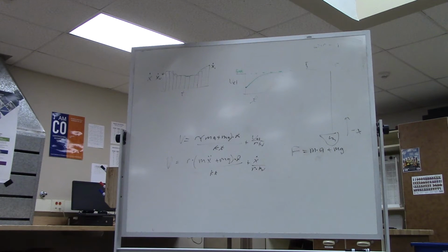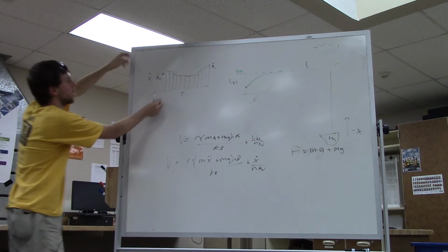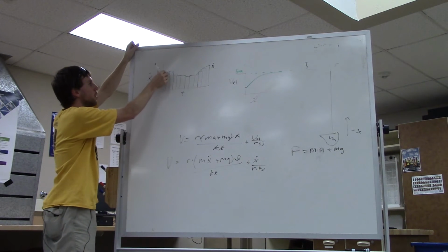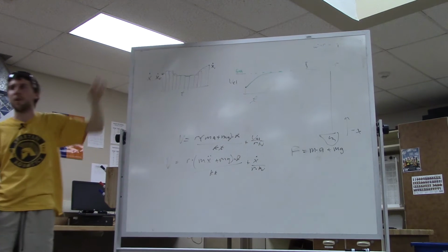Isn't that what the code actually does, where it has a variable that's like a sum, and it just adds to that sum to actually integrate? Yep. Exactly. I mean, that's how you do the integral term in a PID loop. You've got something you want to integrate and a slice of time that value is what we're going to use over, and you just add them up one by one.